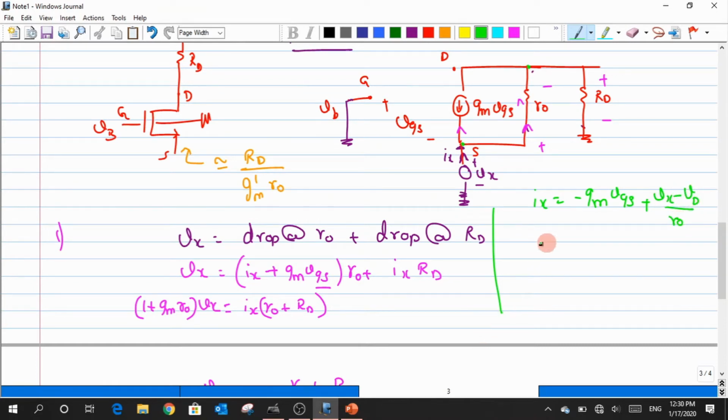Now what is Vd basically? How will I express this Vd? Both these currents which were split actually combine here as Ix, and this Ix is the one that flows through Rd. So you can write it as Ix into Rd. When you do the substitution, you would get the same result. There won't be any change between the results. So at least from here you can just carry on. Just see whether you're getting the same results or not. Are you getting the same results, in case you're working it out?